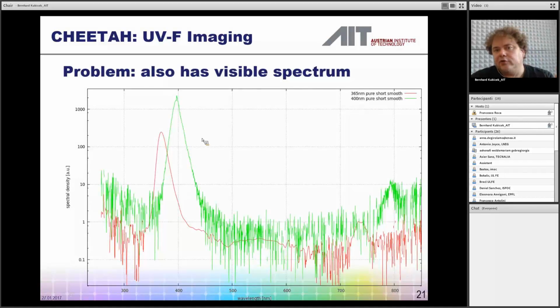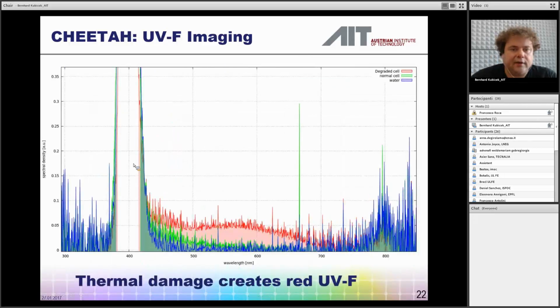If you look at the spectrum of a normal LED, you will see that even a laser has a bandwidth that you might even see with the naked eye. With LEDs, it's the same. So there you need to do some filtering to get optimal contrast. And this is why it's not so trivial to build an illumination source for this.